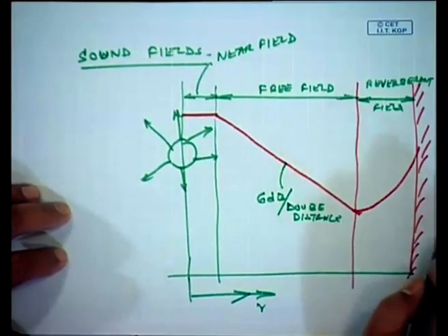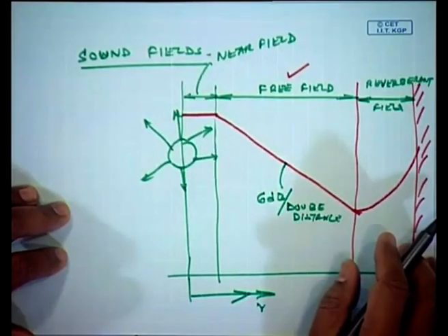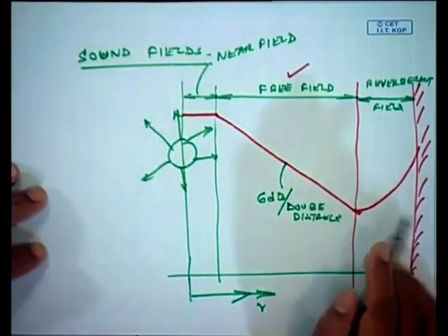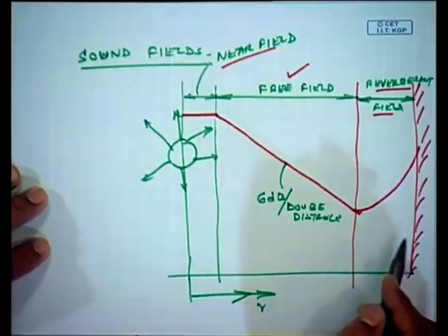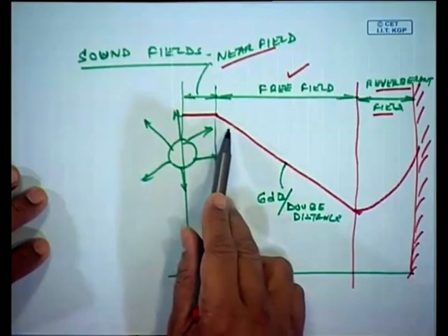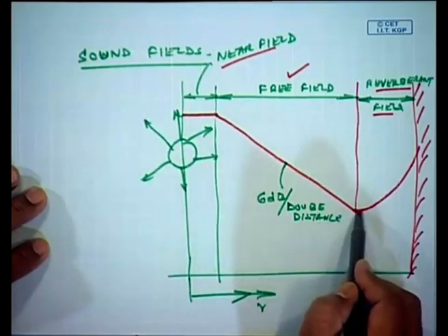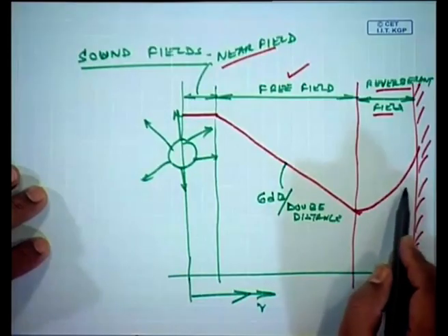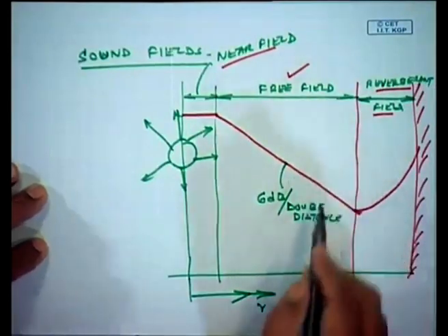Okay. And so, always a good area to measure, as I was telling you, is the free field. So, in noise monitoring, when you say distance from the source, you can also say whether it is in the free field or far field. So, always avoid near field and always avoid reverberant field. In a shop floor you can move your sound level meter or microphone away from the source and see whether this 6 dB decrease is there with doubling the distance, and whenever the level tries to increase, you are close to the walls in the reverberant field. Like you would have seen, if you go to the corner of a classroom and speak, because of the reflections in the wall, the sound pressure level will increase. Okay. And this is what we need to measure in.